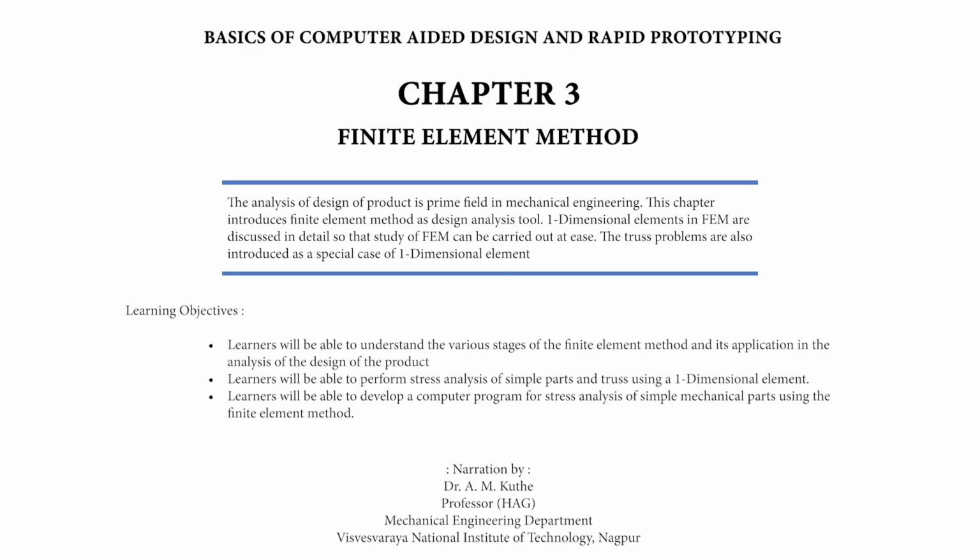Based on the displacement at nodal points, it is possible to get the value of strain and stress over the element domain. It is thus clear that the smaller the size of the element, the more accurate solution can be obtained. It is therefore desired that continuum must be divided into as many numbers of elements as possible, and the elements are non-overlapping.